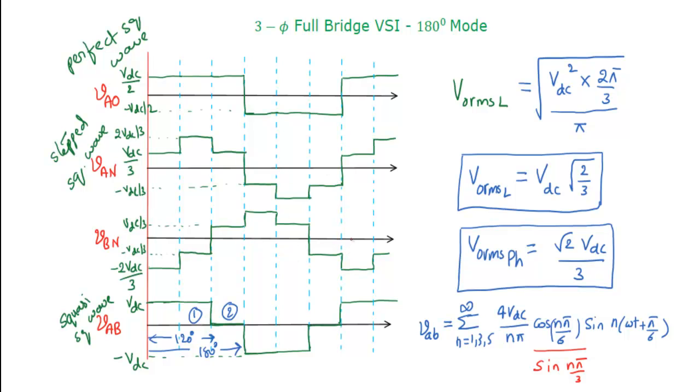But remember here, why we discussed the pole voltage is important. You can see here, if you substitute n equal to 3, either this or this, both will give the same. Okay, no need to worry. If you directly substitute n equal to 3, the 3 gets cancelled, sine pi. Sine pi is nothing but 0. Or you can see that n equal to 3 means it is pi by 2, cos pi by 2 is 0.